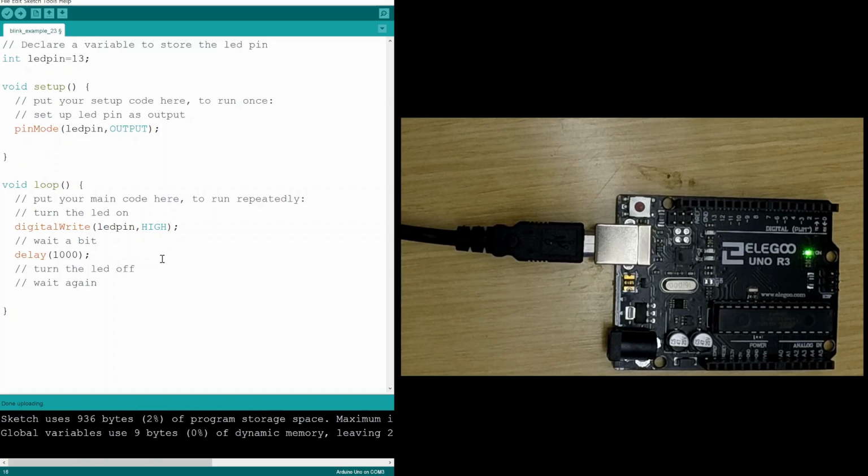So we'll go ahead and start with that as that matches what we're seeing from our factory example over there. And then we need to turn the LED off. It's going to be the same command as before, digitalWrite. We're still writing to the LED pin, but now we're turning it off. So we're going to set that pin to LOW, which will set it to 0 volts, and our LED should turn off.